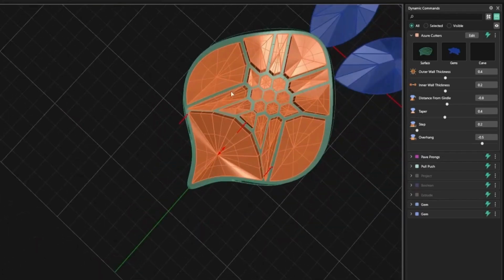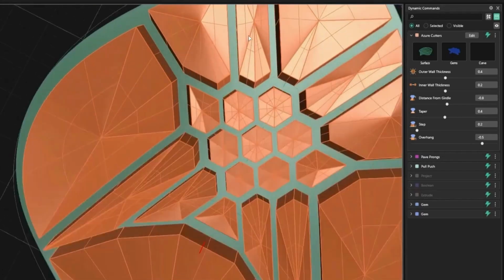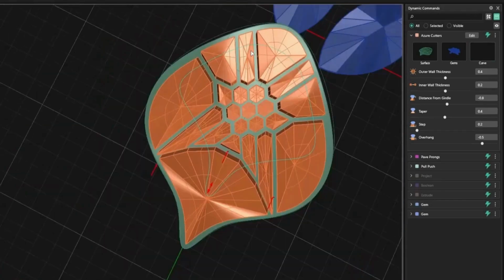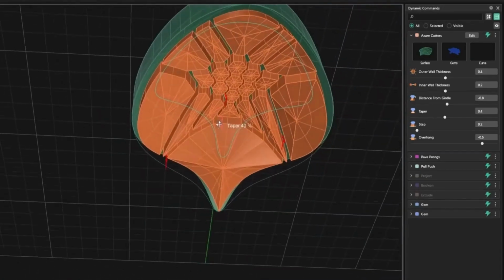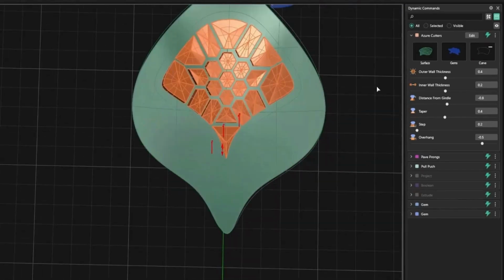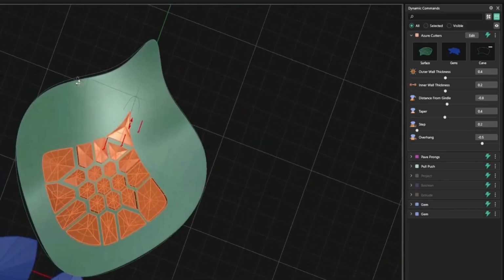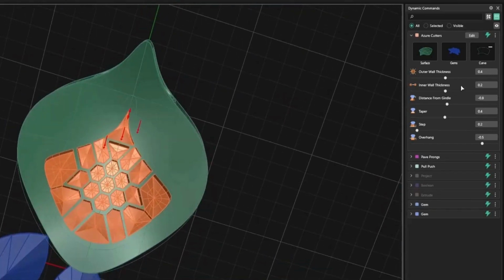In this example, I projected a curve onto the surface. Using that curve as a boundary allows the cutters to follow a custom silhouette. Once selected, all dimensions adapt to the curve's limits. This means you're no longer restricted by the base surface. Your projected curve controls how far the cutters reach. It's great for complex or open gallery work where control matters.